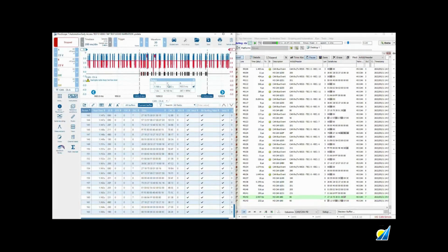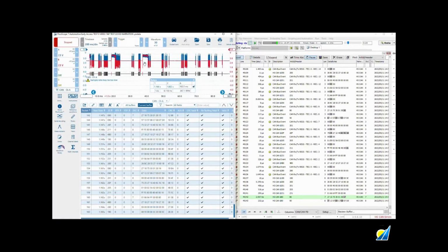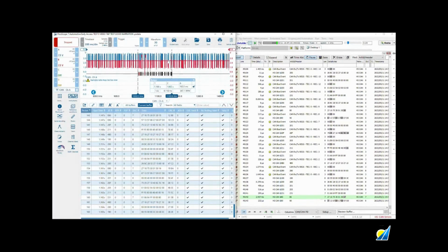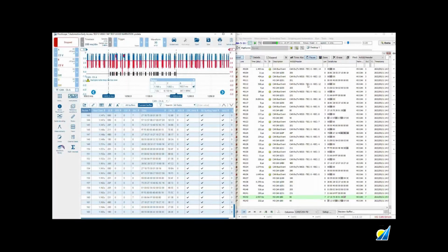So if we look, I've now decoded between the rulers, so rather than decode all data, I'm only decoding from the last received good message to the point where our error counters reverted to 0. And that amount of time was 163.5 milliseconds. So although the bus was restored and everything was fine at this point here, because there was our last event of being driven high, error counters are still active and counting down. So it is good to know that there's additional information beyond what we see here in PicoScope, because we are decoding at a silicon level when we actually decode with Vehicle Spy.